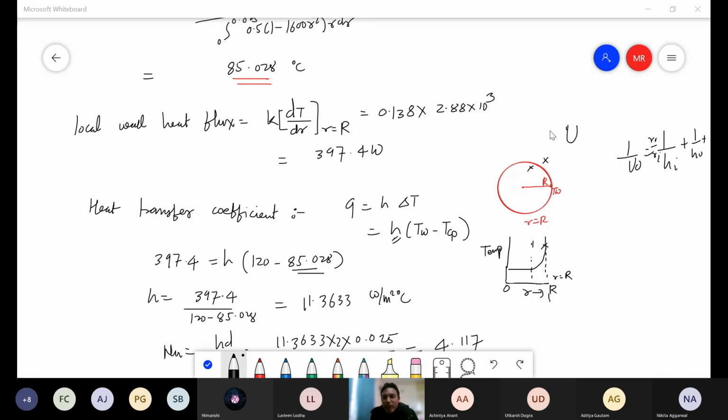So the thermal resistance is negligible, and so we take the whole temperature of the body, and when we calculate the change in unsteady state temperature, then we apply the lumped heat capacity concept and calculate the formula. Sir, if we consider the temperature gradient inside the metal, can we apply the equation for unsteady state conduction in a sphere? Yes, you can, but then you have to solve the generalized expression which we have derived.